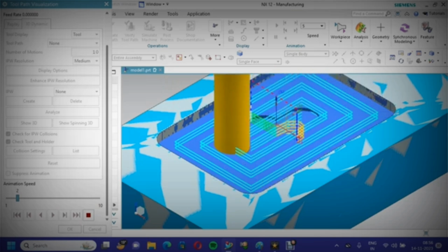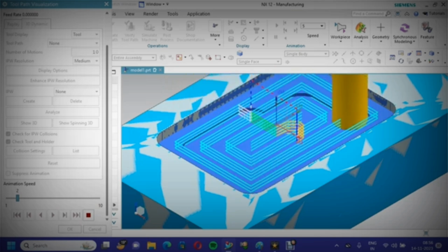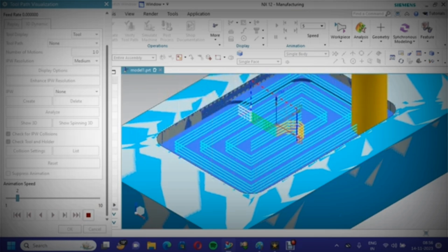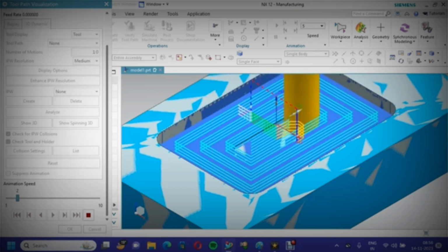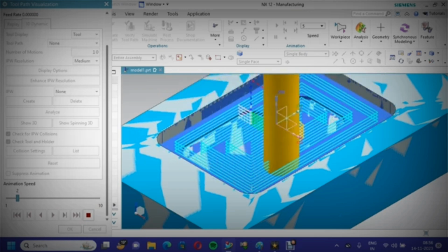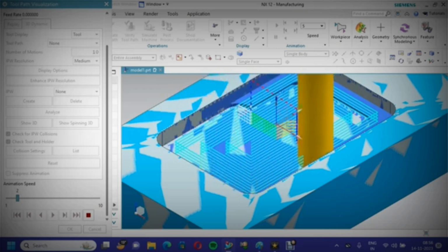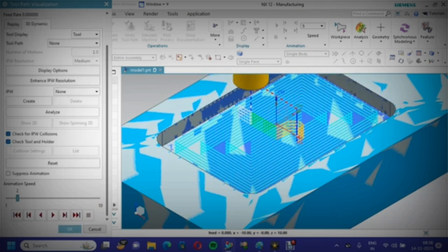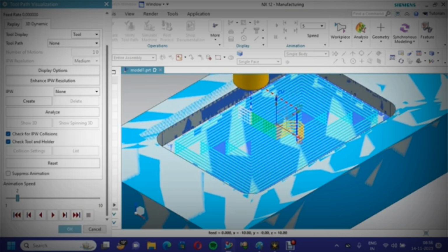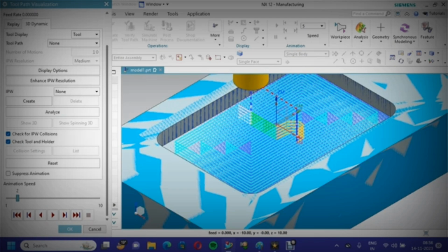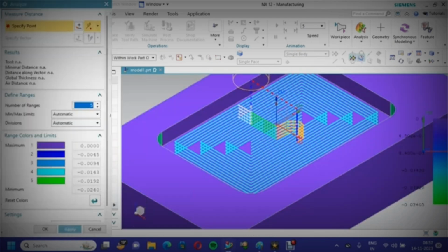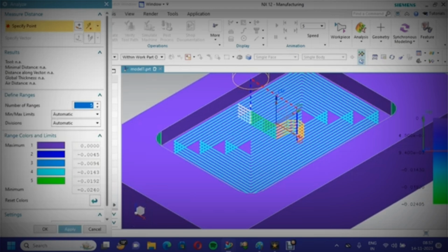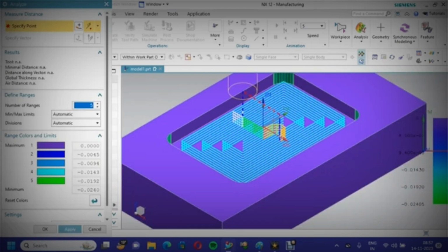It is very important. If you are putting 50, again the time will increase in the CNC program, because it has to travel from 50 mm to 10 mm, and the machine will consume another 10 to 15 seconds. So the machining time may increase. So we have to be careful about each and every reading, we have to analyze it. 0.0 means there is no material, all material has been removed.